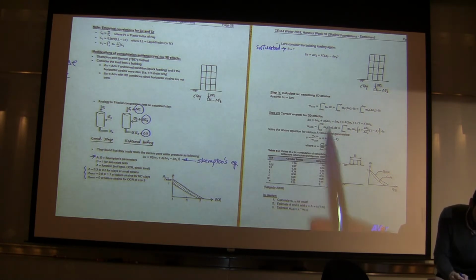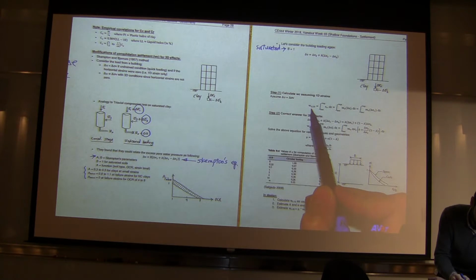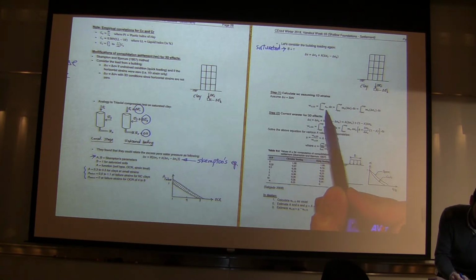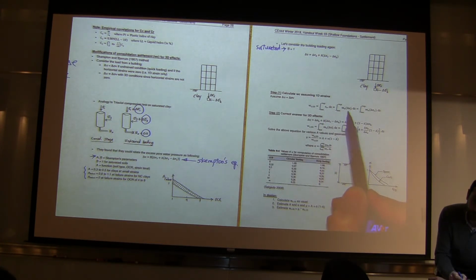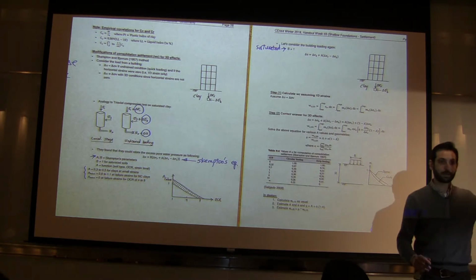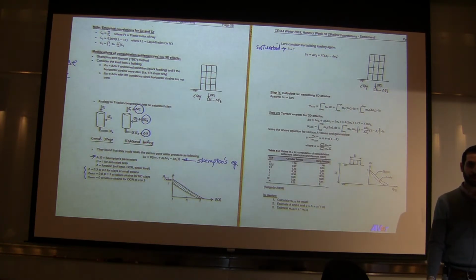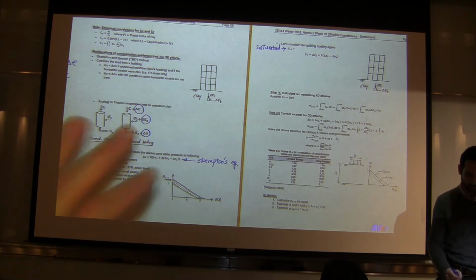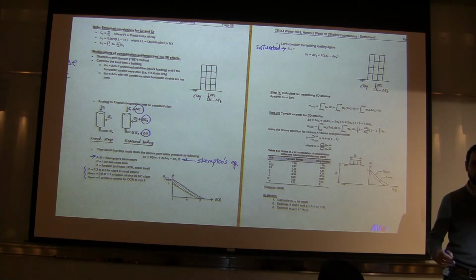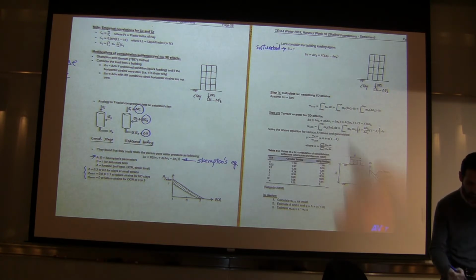Excuse me. So your consolidation settlement is the integral of the strain, epsilon V, and you can replace strain with mv times delta U. If you don't remember what mv is, go back to the notes for soil mechanics. Don't get bogged down with it right now, but it's a parameter that relates the compressibility of soil to the pore water pressure.